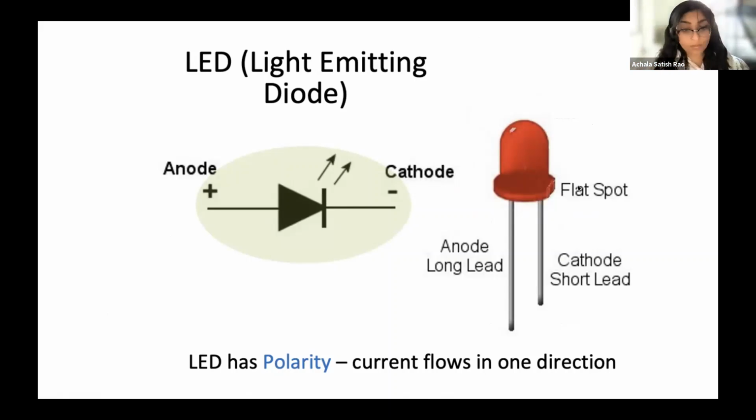You need to wire them in their appropriate respective orientations, or else you risk burning out your LED. With the LED, it's okay. But if you're wiring other things that have polarity incorrectly, like your push button or an op amp, you risk blowing them up and potentially creating a hazard for yourself.